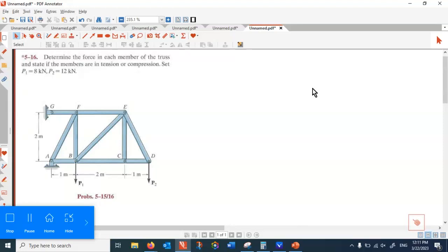First, the method of joint at D. At D, I found the answer. So C is one, CD. So first you find CD. Is there a simplification you want to do before that? Maybe CE is what number? For sure. If that is a zero force member, how does it impact calculation of BC?